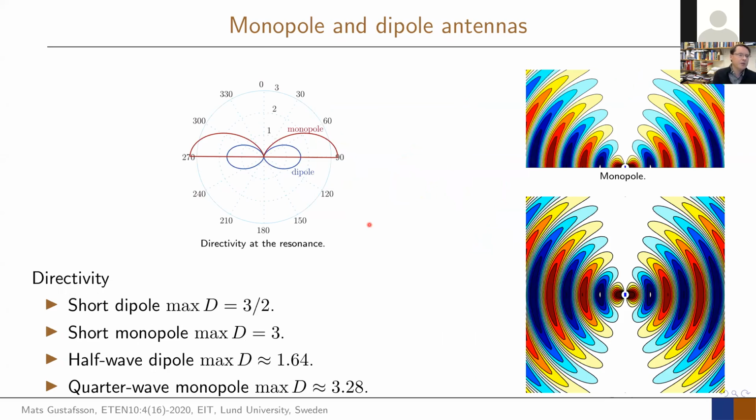And then if you look at the radiation pattern of it, if we draw the same thing, you have your donut shape down here. So here is your typical dipole. And above these ones, you have then the monopole that sits there. And you can see here, the values are, of course, going up to approximately a little bit above 3, if you would take the half wavelengths. So 2 times 1.64, like 3.28 in that case. If you make it a quarter of a wavelength monopole, which corresponds to the half wavelengths dipole. So that is the length that sits there.